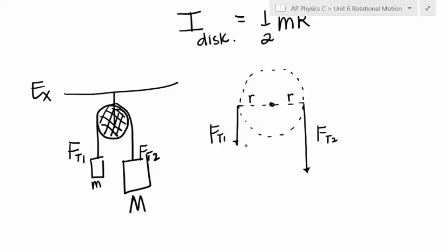If you've ever noticed, a lot of times there will be, like our pulleys that we used that go with the carts, they all have sections cut out in them. It's not just to make them look cool, it's to reduce their mass. So they have even smaller mass so that it doesn't take as much to get them going, and therefore doesn't take away as much of the energy of the system. It doesn't cause as many effects. If that disc is small in mass, then it doesn't matter overall. But now our discs are going to be heavy and have mass and need to be balanced.